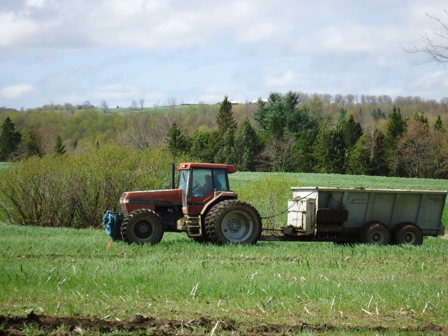Okay, so I included this slide not just because it's a pretty farm picture from the state of Maine, but as a launching point to describe a few of the parameters and particulars regarding land application of Class B biosolids on farmland. In this particular case, dewatered cake at about 20% solids, which is about what typical manures are being spread on a cornfield, using conventional manure spreading equipment that most farms have and is found around.